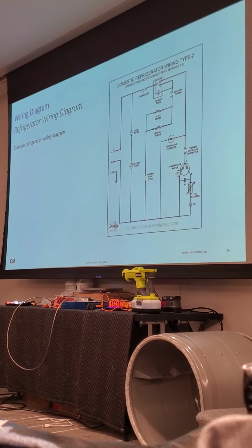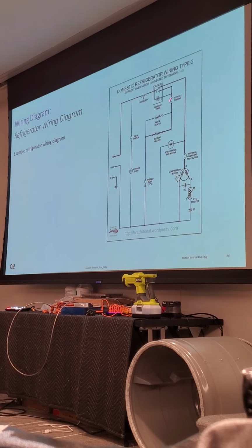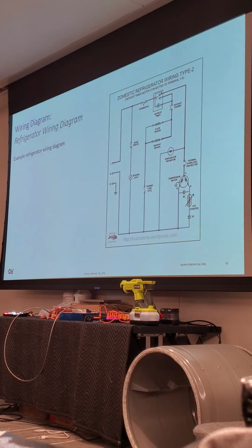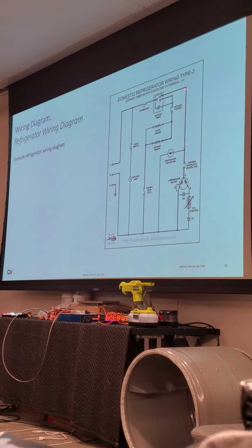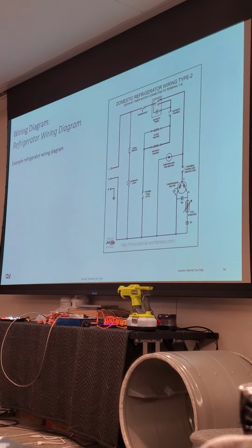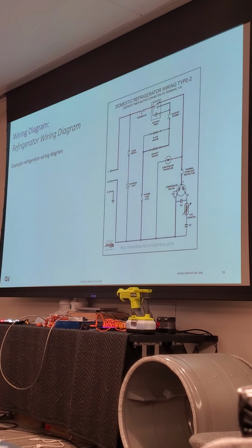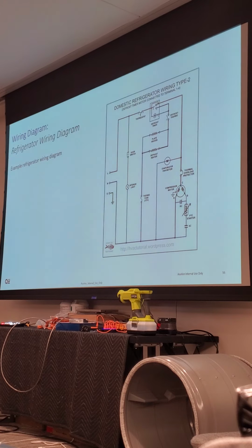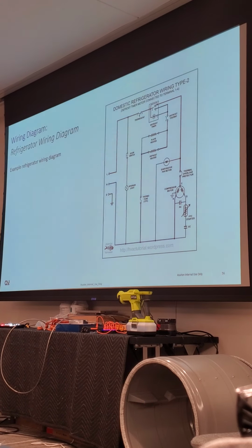Okay? What would this be? It's the temperature sensor? It's a thermal fuse? On this particular type of circuit, that's going to be called a bimetal. Who knows what a bimetal does? Closes and opens based on temperature? Closes and opens based on what it needs for temperature, right?